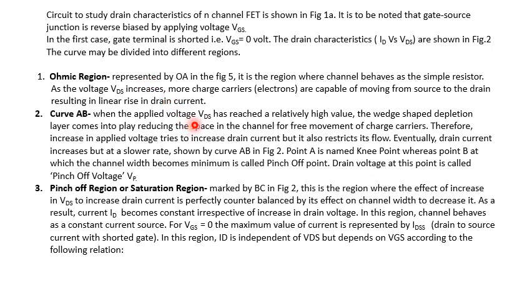Now when we increase VDS continuously and reach point A, due to VDS the wedge-shaped depletion layer comes into being. That is, the wedge-shaped depletion layer is forming, the width of the depletion layer will swell up in the upper portion, and the width of the channel will decrease.